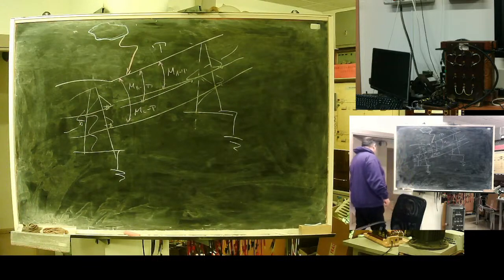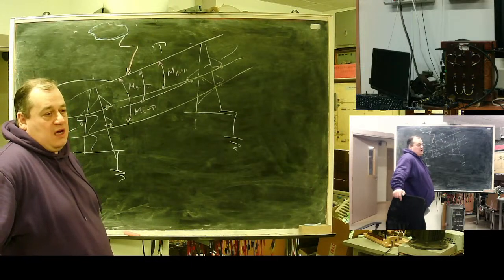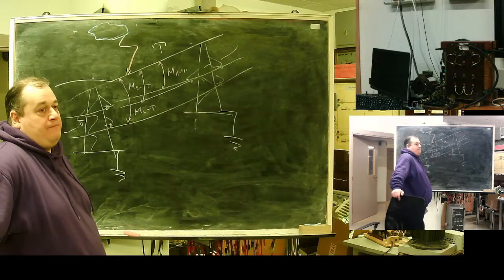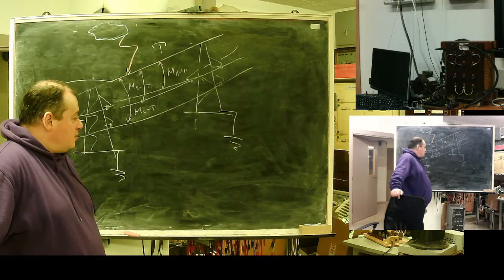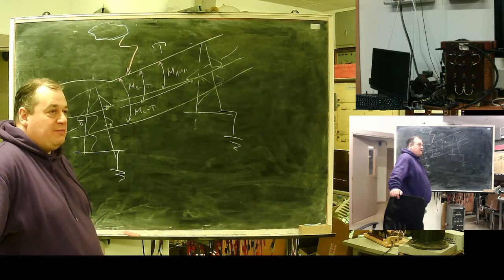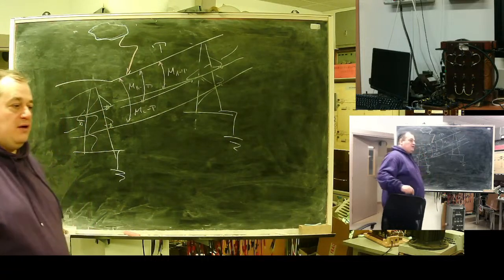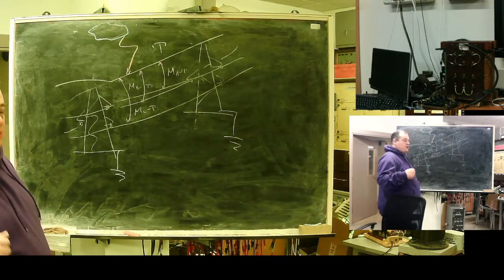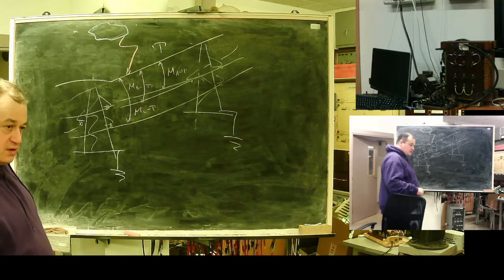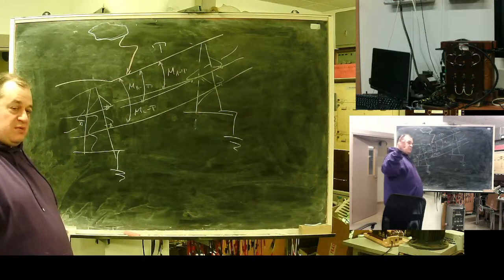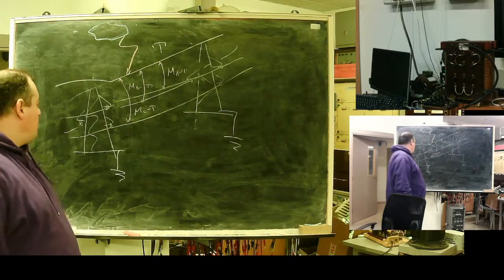Actually, if we speak of land usage, delta is most preferable. Horizontal spacing uses much land, but for higher voltage it's better because the tower is cheaper. For lower voltage, delta is more preferable. For higher voltage, horizontal placement is more preferable.